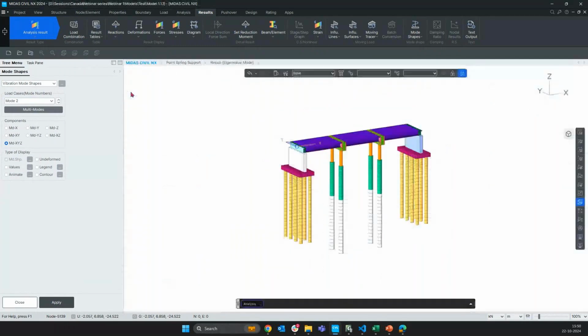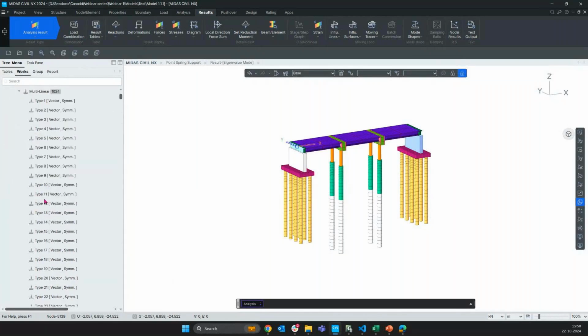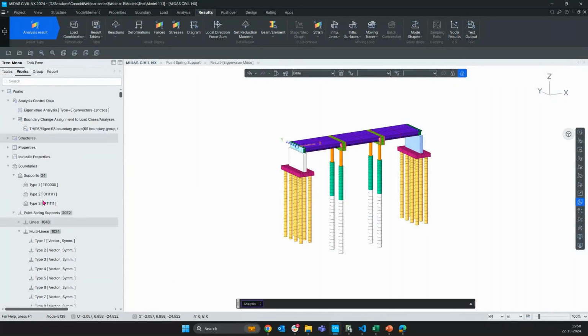Now, the other important thing that we need to always take care in this case is the effective section stiffness scale factors. So the section stiffness scale factors are basically calculated by considering the effective section stiffness, that is I effective.